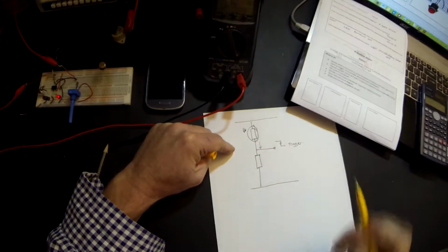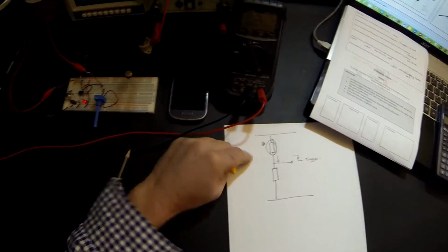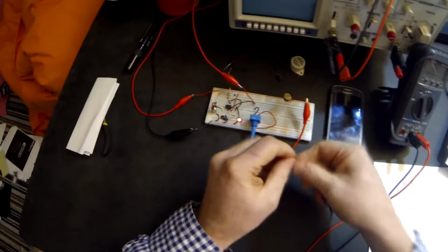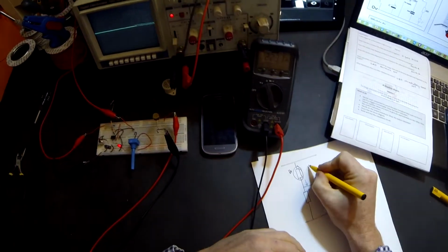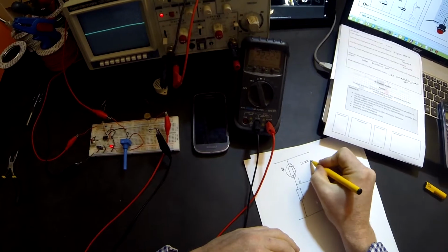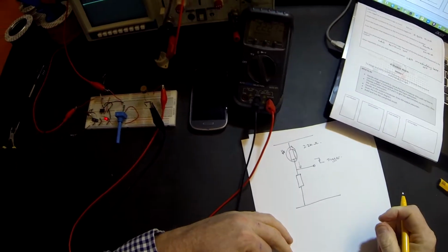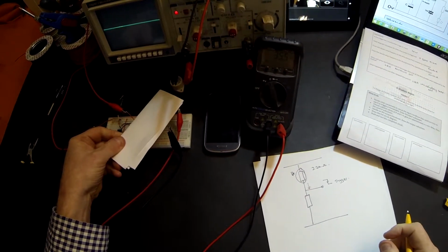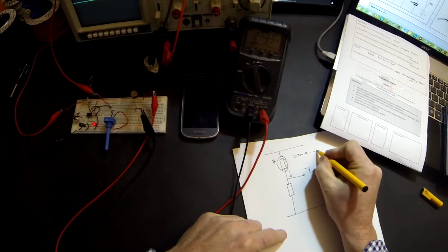Now the question is, what values do we want to use? Well, first of all, let's look at the resistance value of an LDR in the dark and light, so we know what range of values we're going to use. So I have an LDR set up. I'm going to plug my meter in. I'm going to measure its resistance. So at the moment in the light, it measures 2.2 k ohms. And when I cover it up, it rises to 35 k ohms.